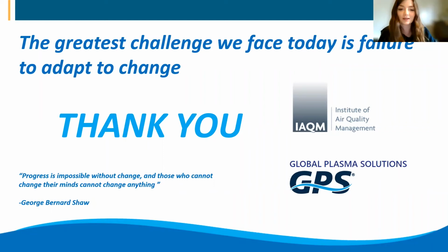Oh, that's really interesting. Thank you. And is there any evidence on how long-term use of ionization technology impacts filter change schedules? More than likely, what you're going to see are additional filter change requirements, particularly at first. And everybody goes, oh my gosh, I don't want any more maintenance than I already have. Here's the beauty of it, though. What ionization can do is make a less efficient filter more effective. It can also make a more efficient filter more effective because the particles are getting back to the filter.